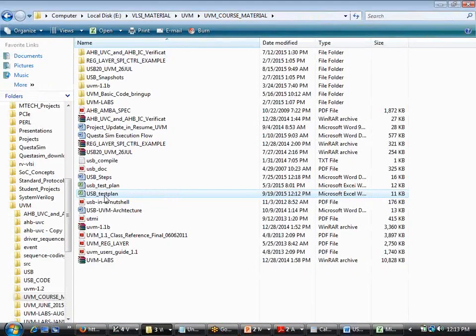So far we have come up with the testbench architecture. You need to go home and prepare that architecture. It's also there in the material. You need to come up with the test plan where you list down features, scenarios, test cases. Understanding the test case is important because it tells you exactly what to apply, then that you should configure it, then initiate speed utilization, then start doing the data transfer.